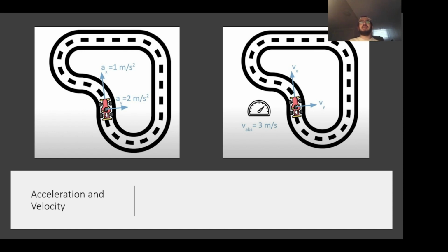Now coming on to acceleration. Acceleration is when the vehicle gets a direction or changes its state in the x-axis or y-axis. It can be longitudinal or lateral. Longitudinal is ax and lateral is ay, right or left with respect to the ground. There should be a respective environment so that we can observe the acceleration. It is also measured with IMU sensors, and it's usually in meters per second squared.